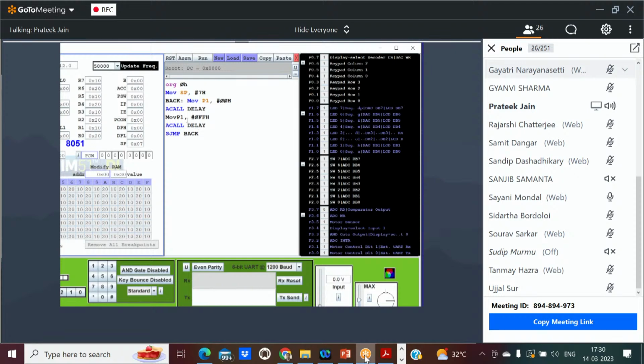So again I am giving the same sequence of instructions in order. First of all we assign the lower value to P1. Again we apply some significant delay. Again we apply the highest value, again and again. By using this sequence we will see the square wave, and this square wave sequence would toggle the LEDs. One time the LED will be blinking, and after some significant delay your LED will not be blinking.